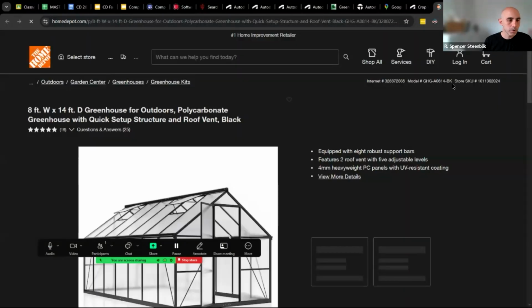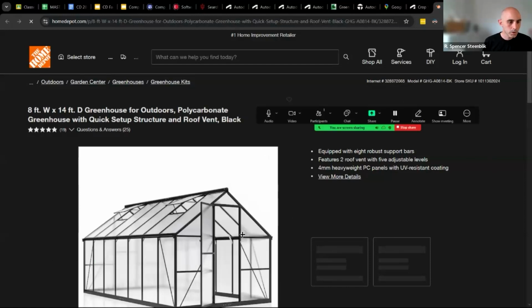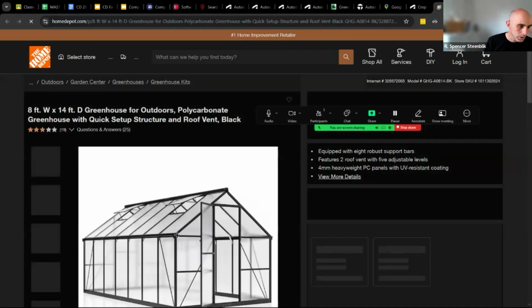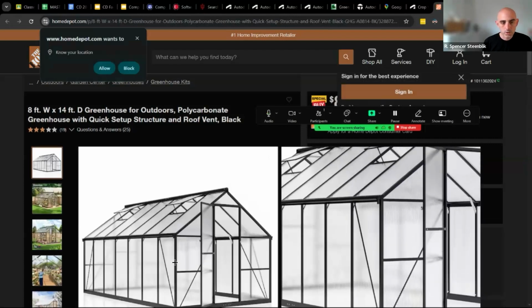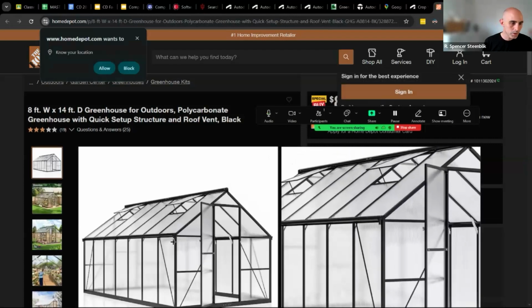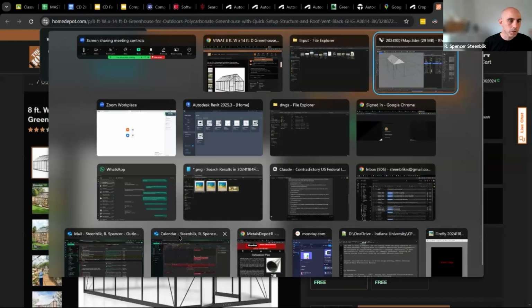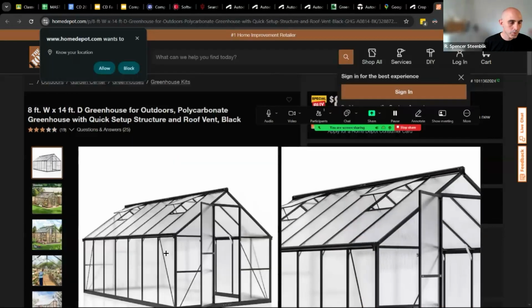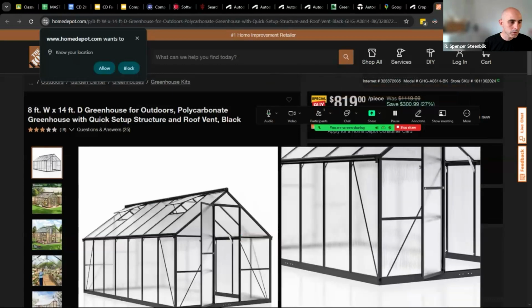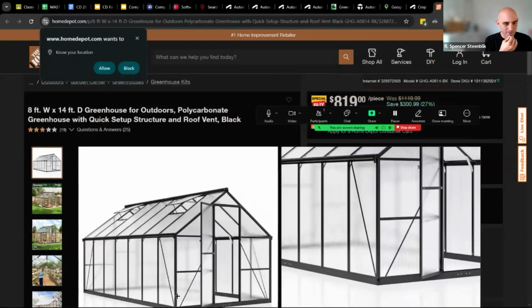I think it's got intermediary struts and such, which are kind of useful. It's got horizontals. This looks like it might be thicker than 1 inch. Probably like 1.5 inches or even 2 inches. We could go on the bigger side here with that. It has a few lateral bracings at the corners.